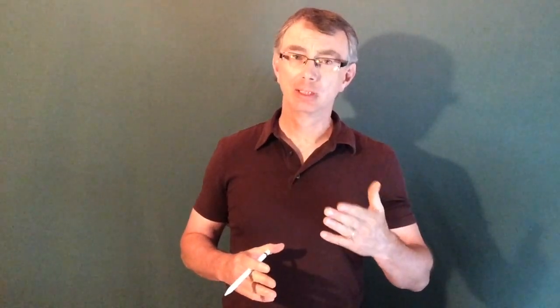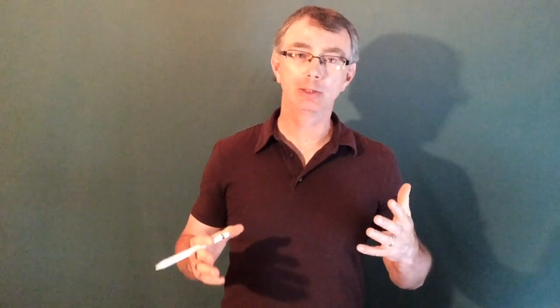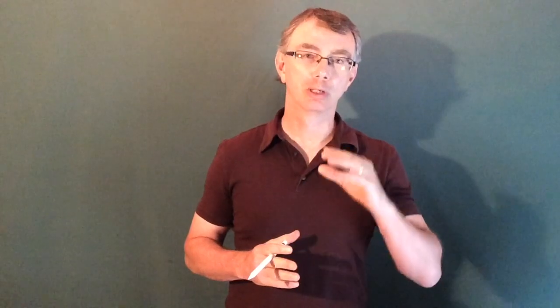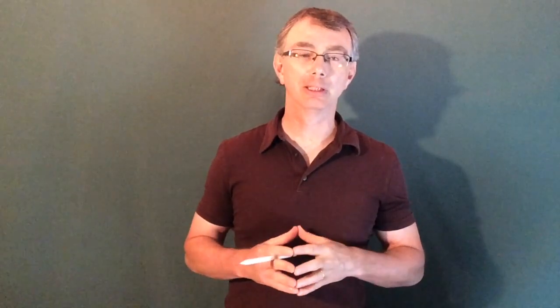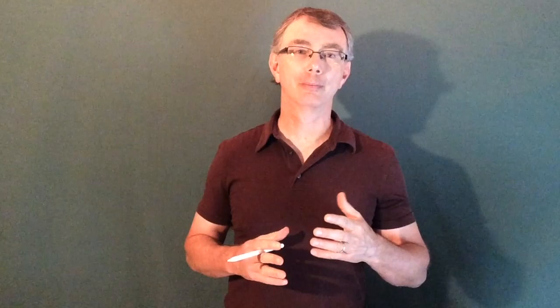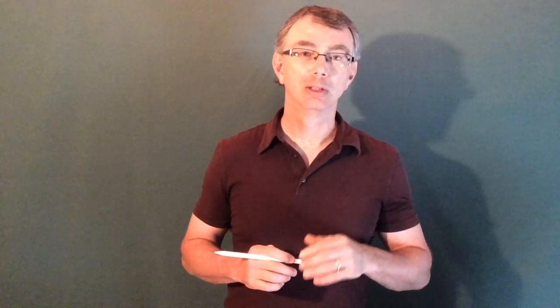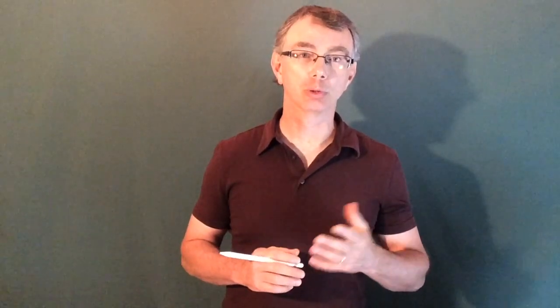Nowadays, manometers are still pretty widely used because they're cheap. But it's very common now to see electronic pressure transducers. They use a piezoelectric approach to measuring pressure, where if you compress a crystal, it'll give off a little electrical current. Those piezoelectric pressure transducers are used very commonly because they're very small and they have very fast response time. So you can measure rapid pressure fluctuations with those kinds of devices.